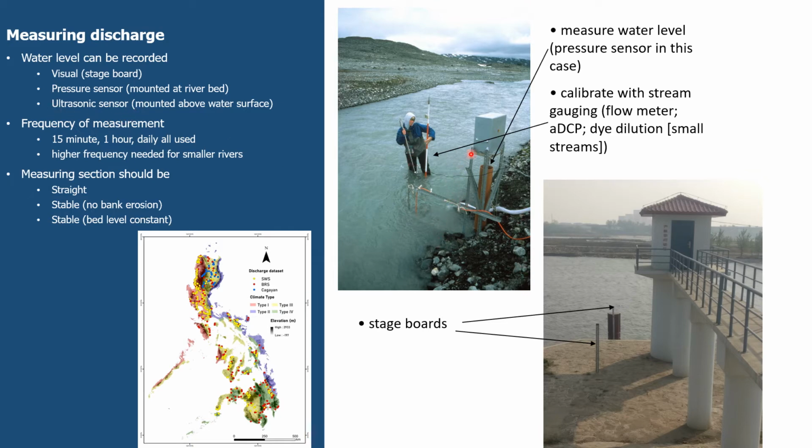On the other hand, more modern sensors tend to use ultrasound, and they don't measure the depth of water. They look down from above and they send out a sound wave which bounces off the water surface and tells you the elevation of the sensor above the water. And that's what's in this construction here in China. They have an ultrasonic depth or water level measurement device that points downwards.